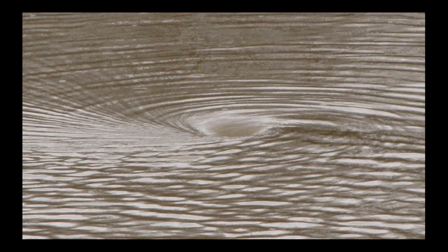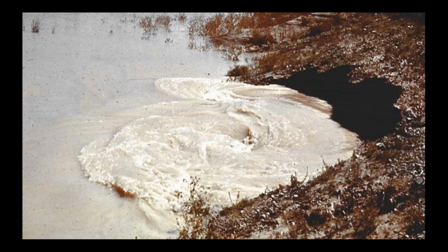This one is a little bit more obvious, and it could be related to a sinkhole developing in the dam, but it could also be the riser structure that's submerged, and that is a vortex related to that. So it's important to know why it's there, the location, and what's going on. Now, if you see something like this, now we're into an emergency mode. This is really getting serious, and we have a sinkhole and then uncontrolled seepage through the embankment.